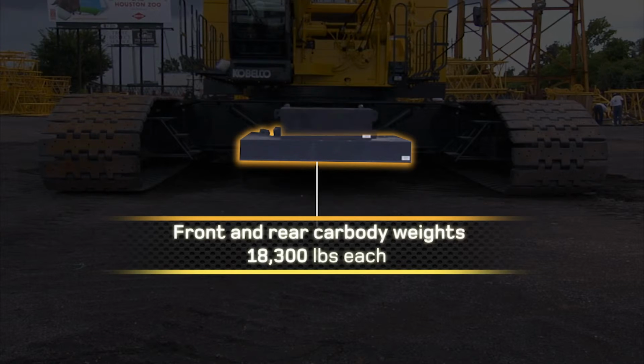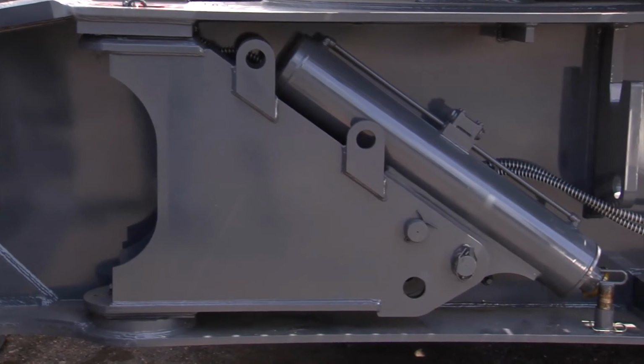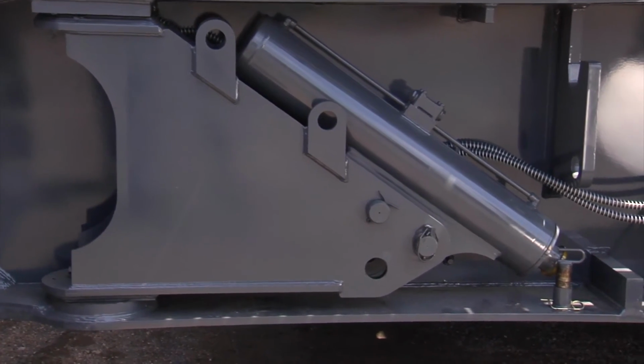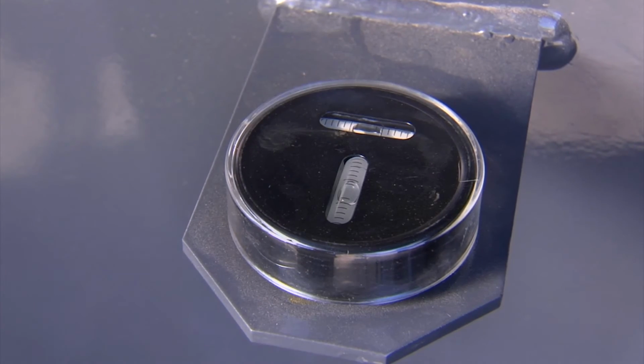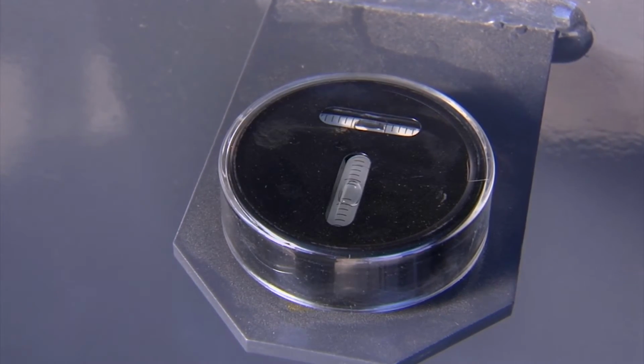Located on both the front and rear of the lower machine are the car body weights, weighing 18,300 pounds each, and a B or C counterweight piece that weighs 11,900 pounds. These are secured to the top of the car body weight. We also have the 4 translifters used to support the machine when removing or installing the 51,800-pound crawler frames. We have 2 bubble levels mounted to the car body frame as an aid to keep the machine level.